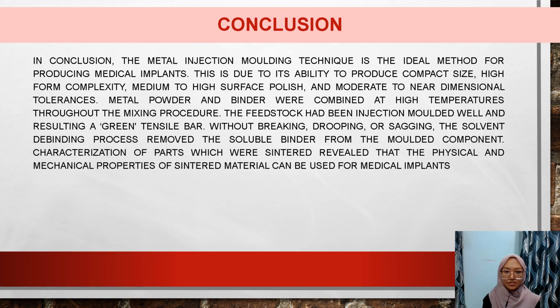The conclusion of this review is that the metal injection molding technique is the ideal method for producing medical implants. This is due to its ability to produce compact size, high form complexity, medium to high surface polish, and moderate to near dimensional tolerance. Metal powder and binder were combined at high temperature throughout the mixing